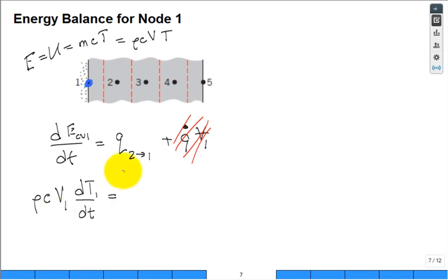And then we have this rate equation. Well, how does it flow from 2 into 1? By convection, conduction, or radiation? Conduction. What does our basic discretized Fourier's law look like? It looks like a K, an appropriate area over an appropriate length, times the temperature difference driving the flow, T2 minus T1. Now at this point, we follow what is commonly used in engineering. We have a temperature and we have it at different nodes.